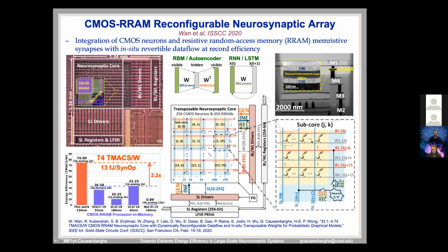So rather than having those typical transimpedance amplifiers that clamp your outputs at 0 volts and collect currents across this array, which is a very power-consuming operation that limits the efficiency of those crossbars, here what we did is we just let it float and let voltage accumulate, and let the equipartition theorem play out. So the energy actually consumed in the process of this crossbar doing its computation is just given by capacitance times voltage squared of the excursion on this node, and that is just femtojoules because you have just a few femtofarads of capacitance on each node.